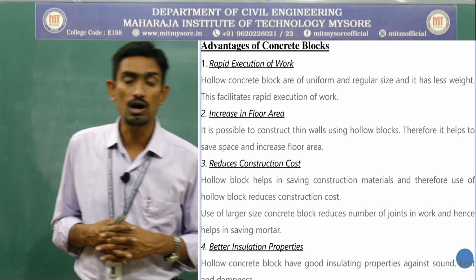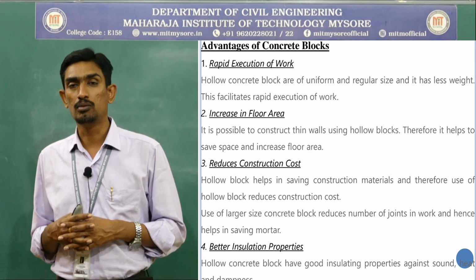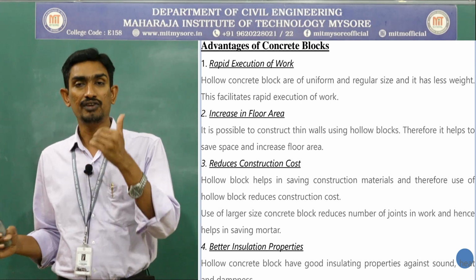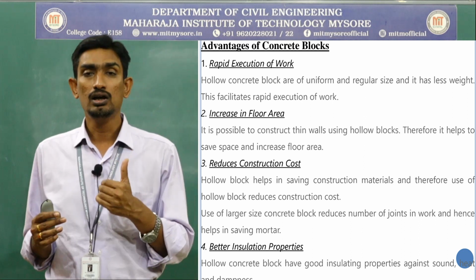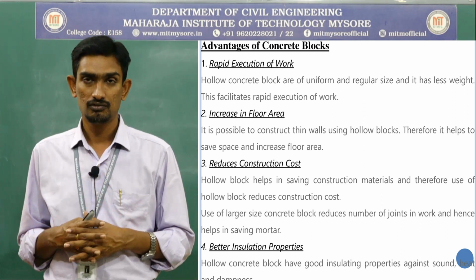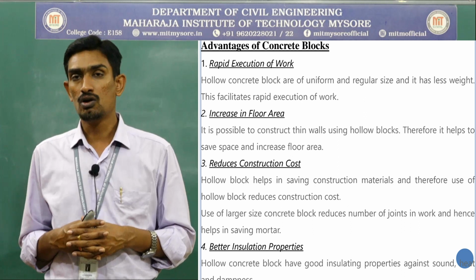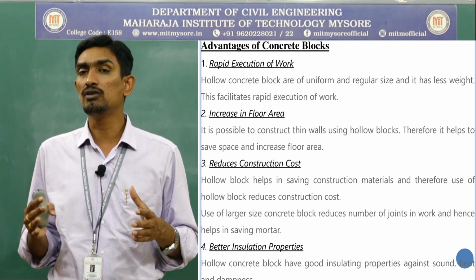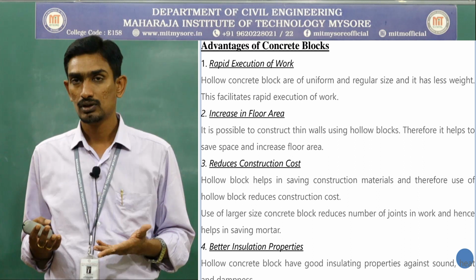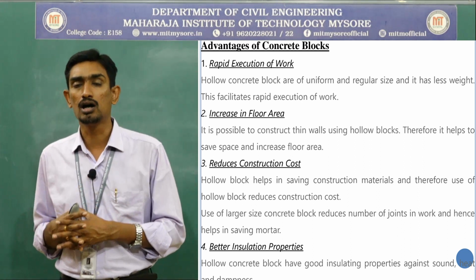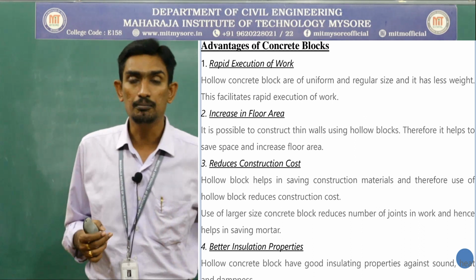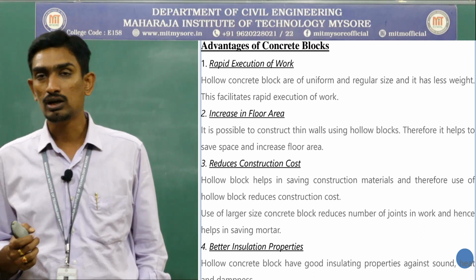If you construct a wall with a solid concrete block, and that particular wall is facing the sun, then the wall will receive more heat. Obviously inside the room you will feel more warm. Is it clear? If you want to reduce this, go with a hollow concrete block so that you can reduce the temperature inside the room.